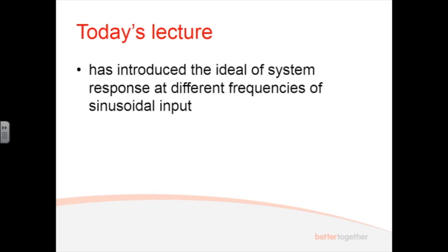which isn't going to cause too much damage, and I can get this same frequency response data just by looking at that perturbation. I don't have to make large changes in what's going on, so I can extract this information on a working plant. I can extract this data, frequency response tests, on working equipment, without troubling it too much. I have to give it a little bit of a shake, I have to put a little bit of a sinusoid in to see what's happening, but I don't have to make massive changes to its operation. So all in all, it's a really powerful tool to use frequency response information.